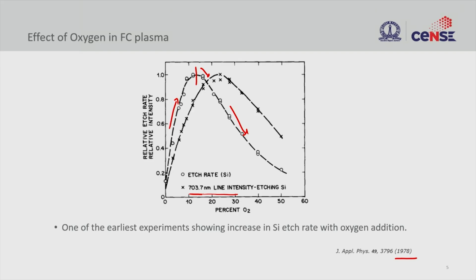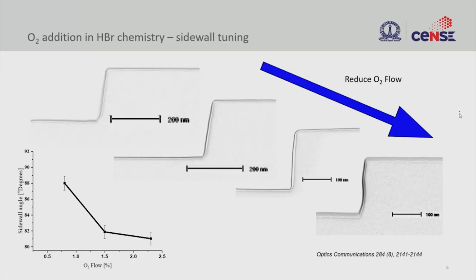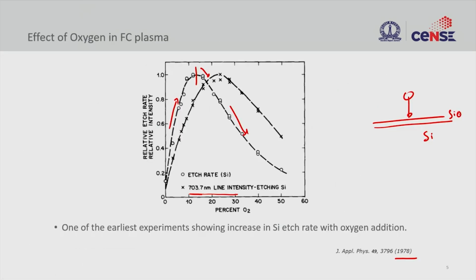So it's the combination of dilution and formation of oxide on the silicon surface. The oxygen radicals come in and form a very thin layer of silicon dioxide, which prevents your fluorine from reaching the silicon. So there is no reaction here, or the reaction rate is very low.